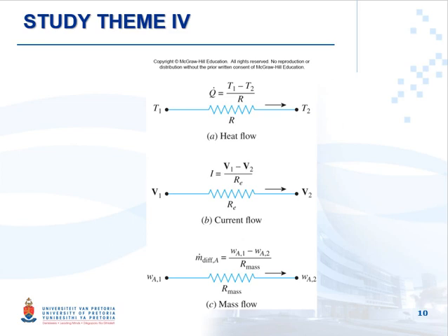You can see here for heat transfer we said that basically for all of them we have a driving force divided by a resisting force. In heat transfer the driving force is the temperature difference, and here the m dot diffusion is important for us, and the driving force is the difference in concentration, a different format of expressing it, divided by R mass, which is the diffusion resistance.